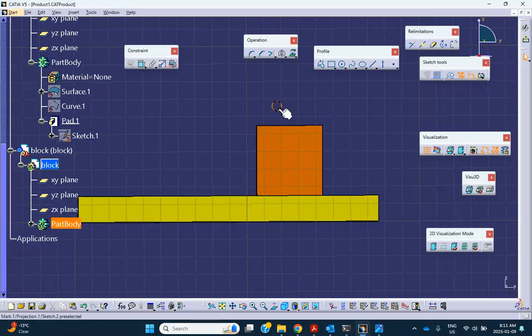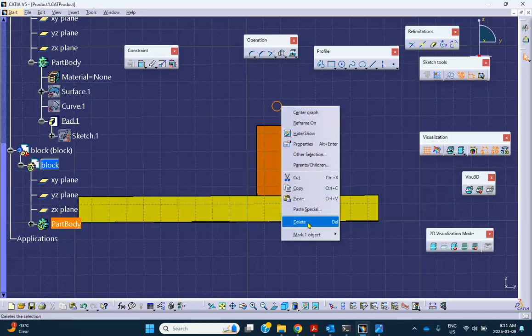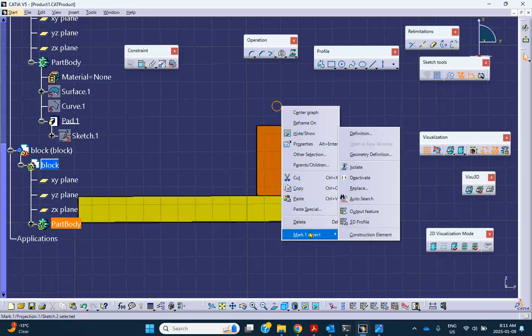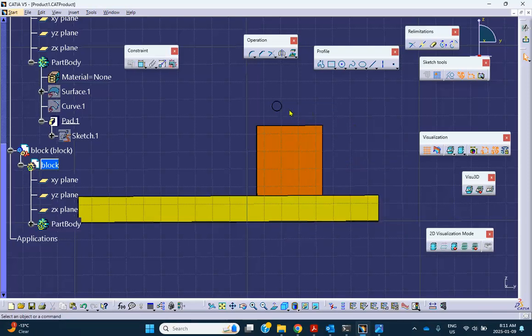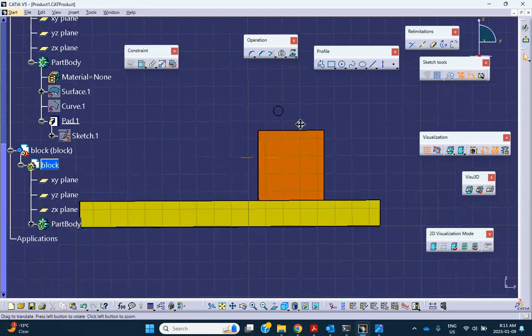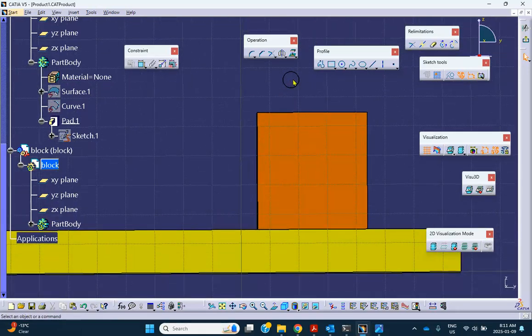The only thing is that I cannot move this. I want to put that thing in there, but I cannot move it because this is a projection. What I can do to free it up, right click at the very bottom, isolate. When you isolate it, then it's really not a projection. You can grab the center of it and start moving it, or we can grab this thing and start moving that. Okay, fine. If it was too much, we'll just draw a circle here.